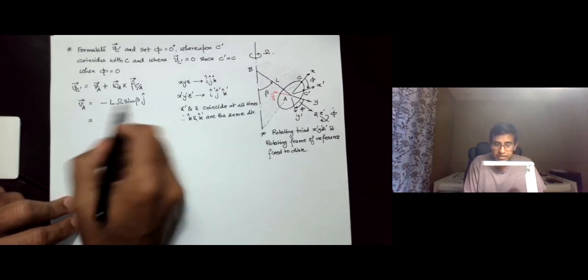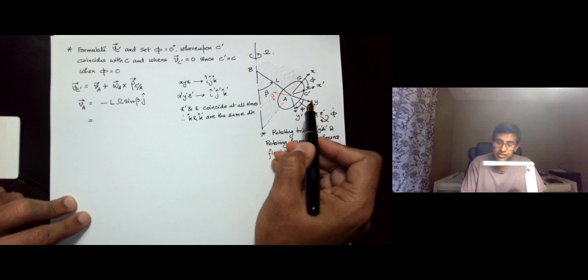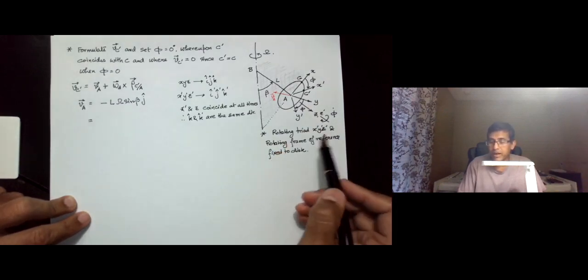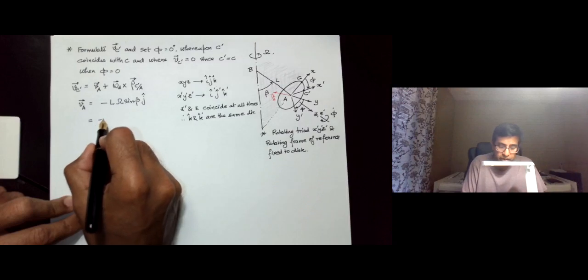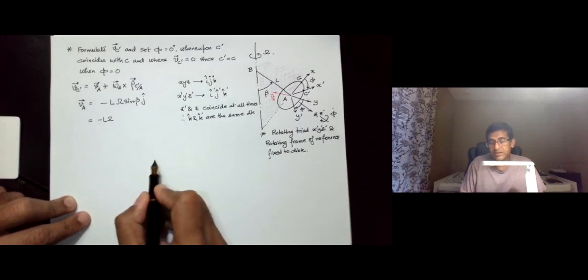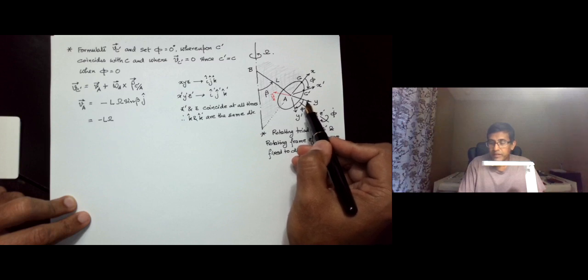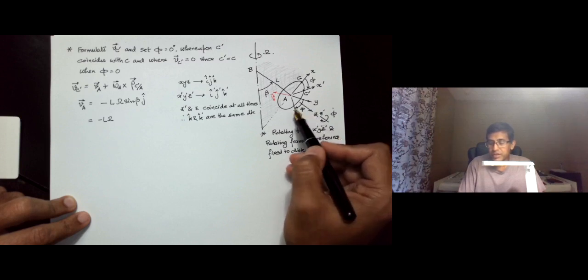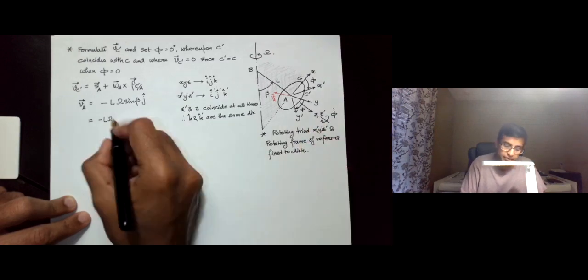So now the velocity of A is in the j direction and j is in this direction. Now we are working with a rotating triad which is along x prime, y prime, z prime. So we need to resolve this j, and you can see that j resolves to cosine phi j prime plus sine phi i prime.